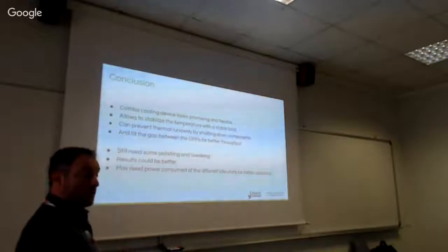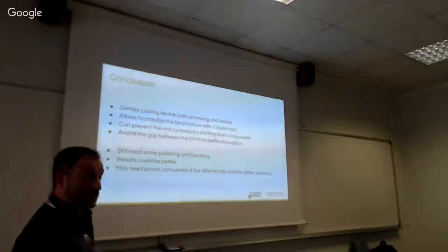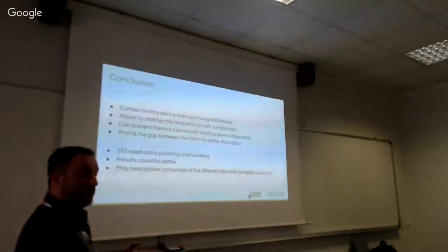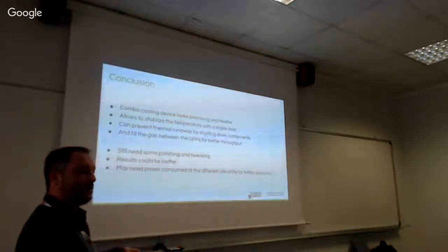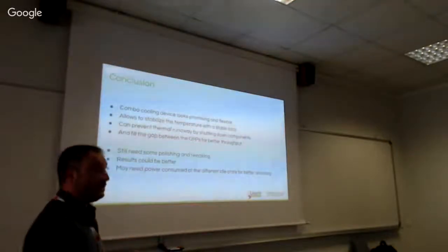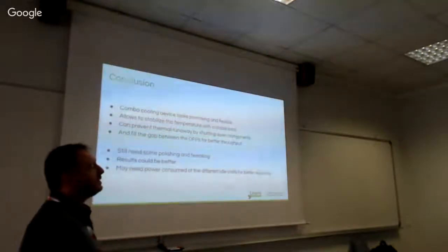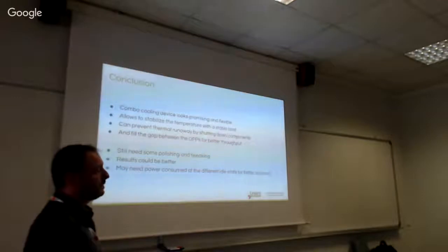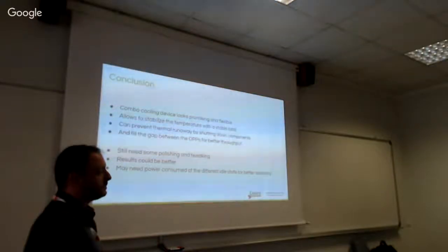What I can do is split the idle injection and create an idle injection framework, but not in the thermal framework. Idle injection is power clamping; it's a power clamping concept rather than just thermal, because you can also control the power budget.